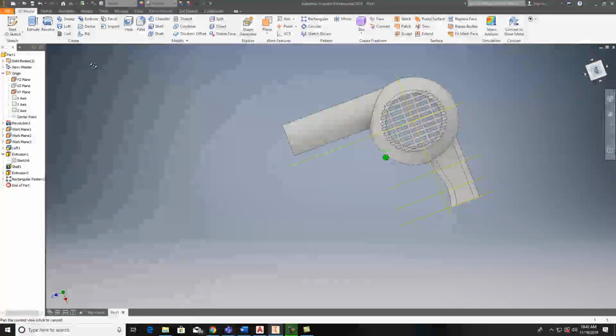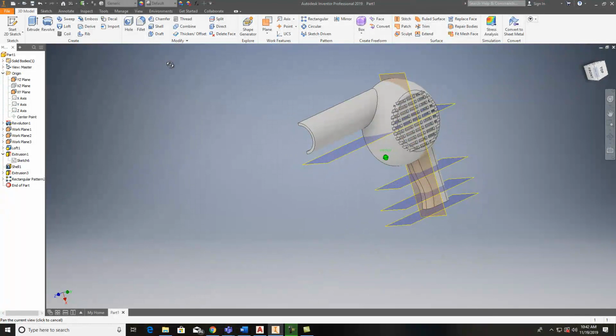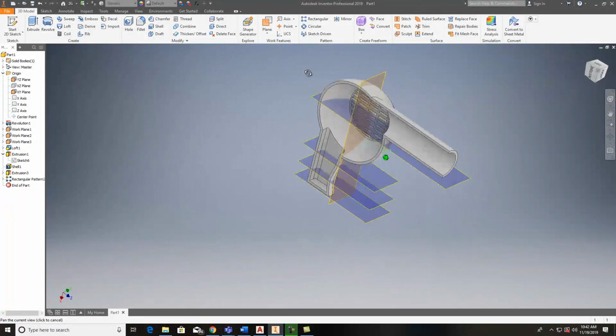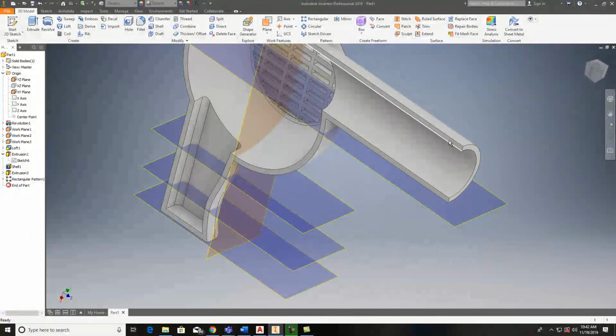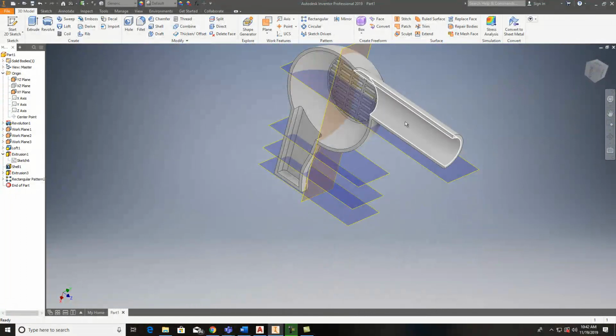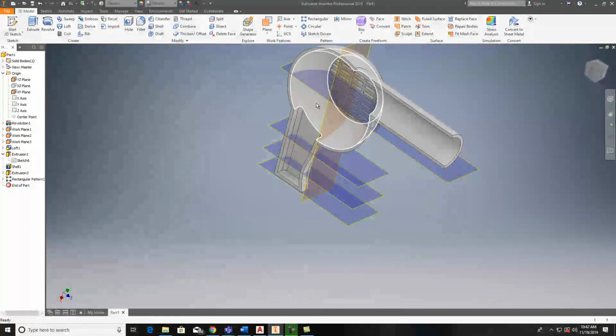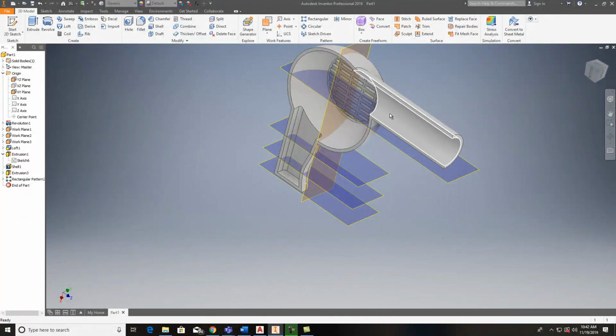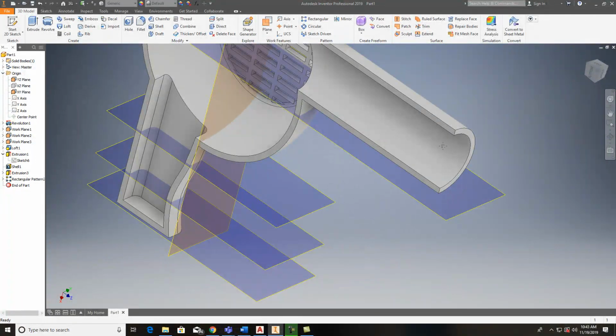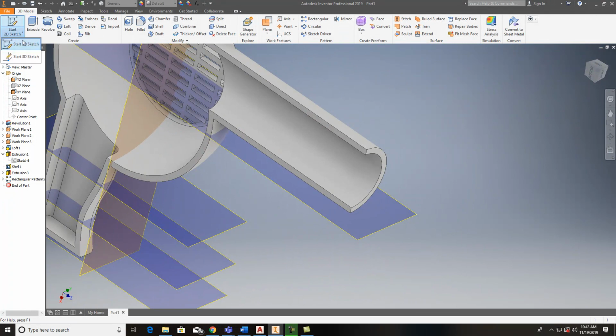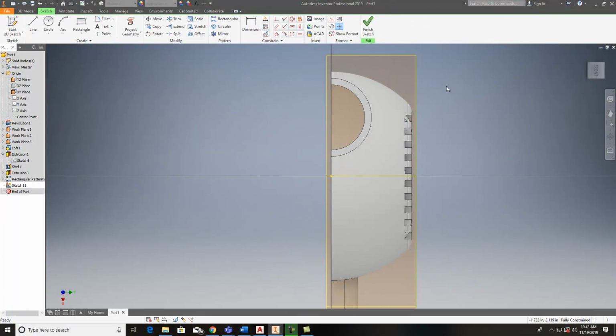Now I'd go back in, and we want to be able to seam this one onto the mirror image of this. When you put these together, you'll have 2 plastic pieces, and the inside would be all the electrical components. So how to do this is make yourself a new sketch right on the face of that. In your book, it shows in here rectangular.